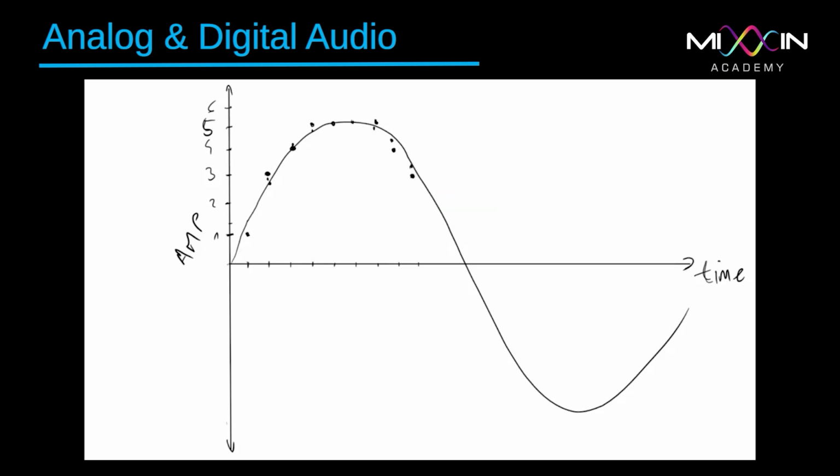So now if we needed to make the signal analog again out of this digital one, see these dots that we have as results, like this one, that one, that one. Now we get a completely different signal because our resolution was bad when we sampled it. It's called sampling. So taking these discrete values in time is called sampling. So once we sampled it, we had a really bad resolution. And now, on account of that, once we recreate that signal so that we could actually play it through our speakers, the reproduction is really bad.